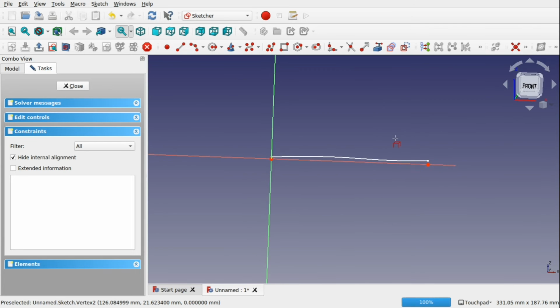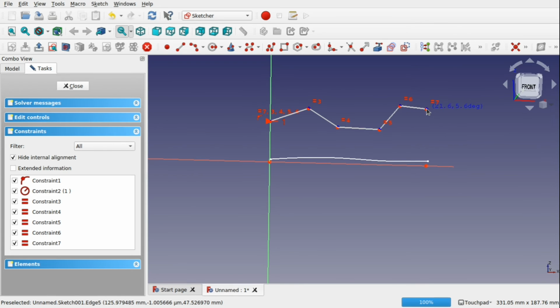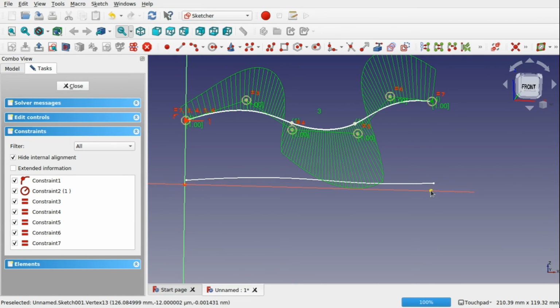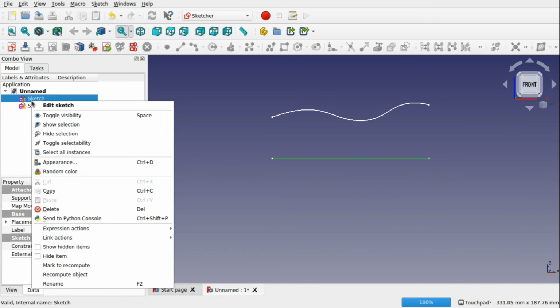So let's project that in. There we go. And we can use a curve in here, so I'm going to attach it to there and just curve this through. Hit escape again, and then these two points. Click those two points and give them a vertical constraint so those are in line there. So that can't be moved, it can only move up and down that line. Let's close that. So let's experiment with these two. Quick rename.